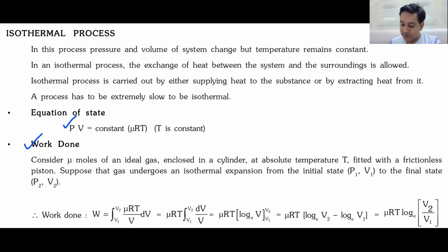Here, the work done will be given by this formula. Do we know this? nRT log V2 by V1. Yes or no? Instead of writing nRT, you can write P1 V1, or you can also write P2 V2. Do you understand this?